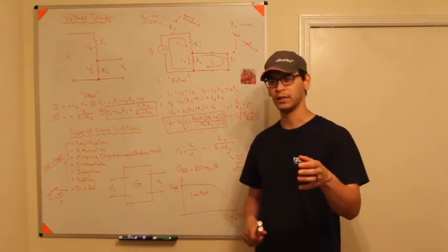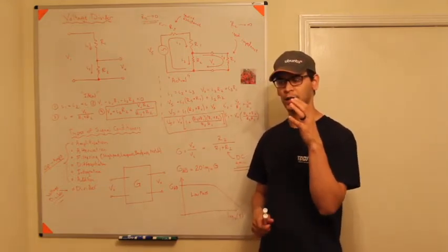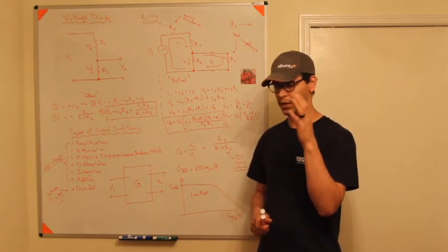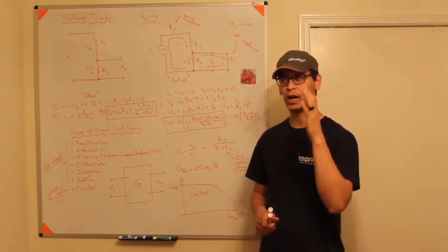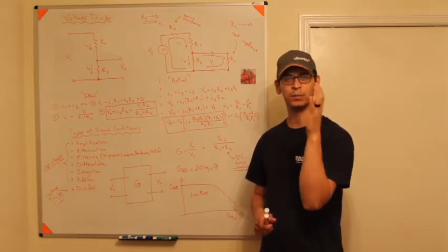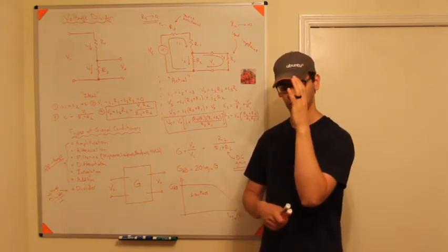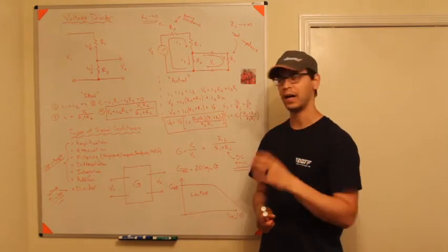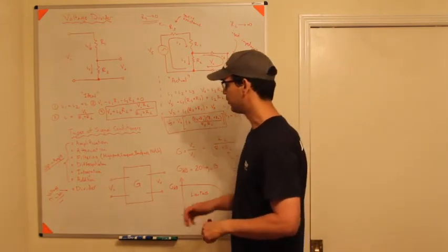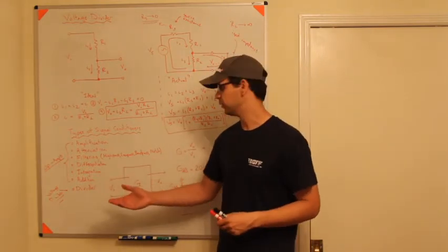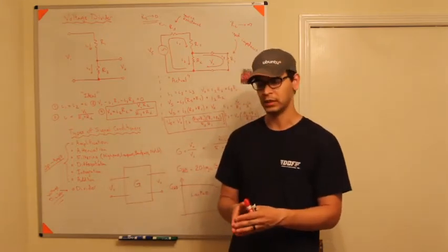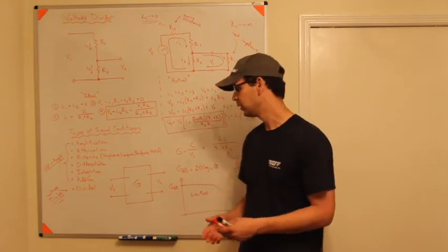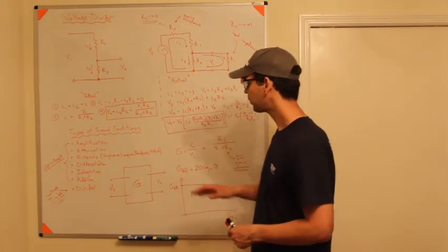That could happen easily from bending modes, or mode shapes of something. If you have a rocket that has a certain specific bending mode, when the rocket fires, you might want to filter that out in your control law. You may also want to differentiate your signal, or integrate your signal. You may want to add two signals together or subtract two signals. You might want to do things like that.